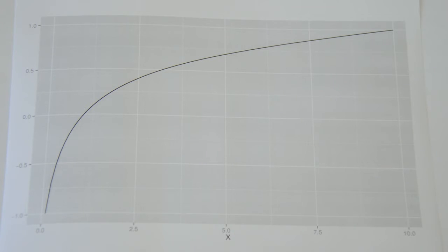But on the other hand, if you are interested in these strong signals as well, and you design your instrument such that it is able to handle them, you're probably going to lose in sensitivity on the weak signals. So one way to cope with that is to use a logarithmic transfer function, which is what I have plotted on this graph here. The x-axis here is the input, and the y-axis is the output, and the graph here is just essentially y equals log of x.